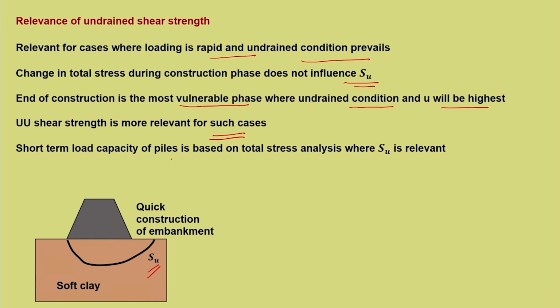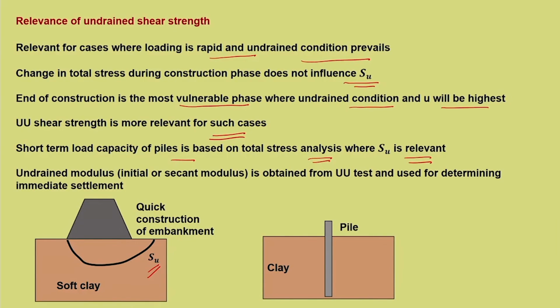Short term load capacity of piles is also based on the total stress analysis where SU is relevant. I hope you remember in foundation design for piles there is a short term analysis where we consider that the soil exhibits an undrained behavior. In that case, what we have is the undrained shear strength SU. So, for designing of piles or determining the pile load capacity, one needs to know the value of SU. So, that is what is shown here.